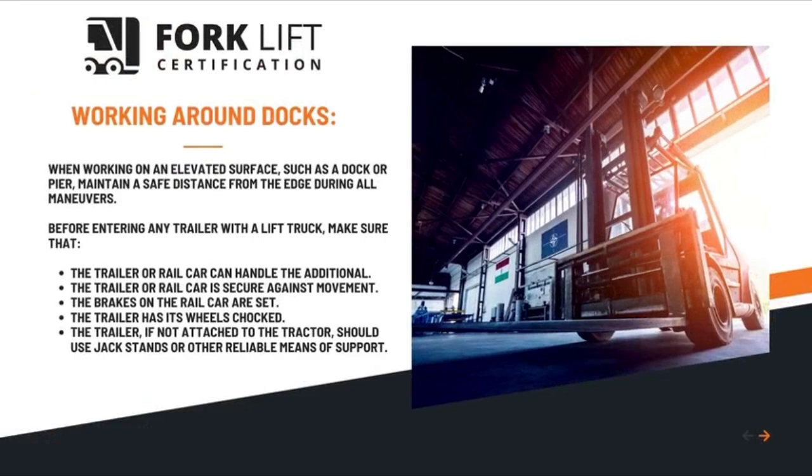Working around docks. When working on an elevated surface, such as a dock or pier, maintain a safe distance from the edge during all maneuvers. Before entering any trailer with a lift truck, make sure that the trailer or rail car can handle the additional weight. The trailer or rail car is secure against movement. The brakes on the rail car are set. The trailer has its wheels chocked. The trailer, if not attached to the tractor, should use jack stands or other reliable means of support.